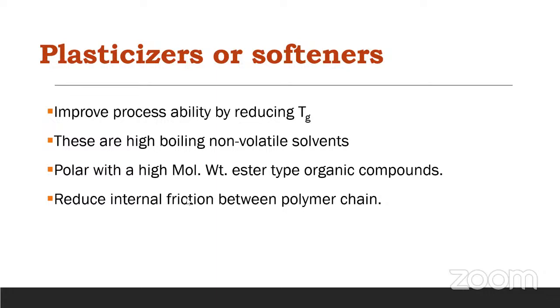Now coming to the plasticizers. Plasticizers are generally molecules which increase the flexibility, the softness, and the processability of your polymers. They are generally responsible for making rigid polymers like polyvinyl chloride or polystyrene more flexible.